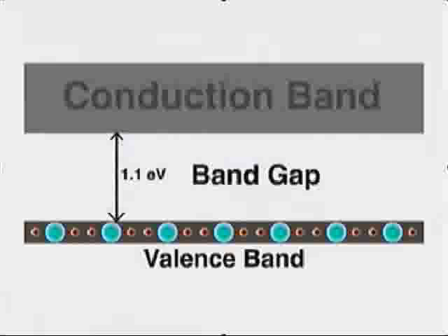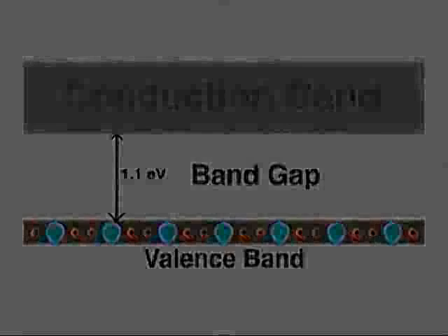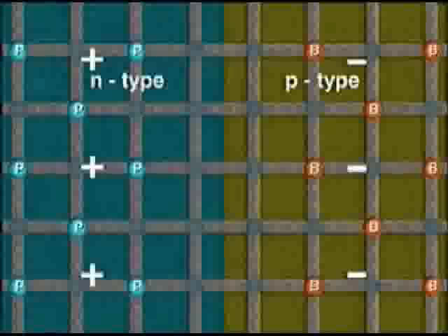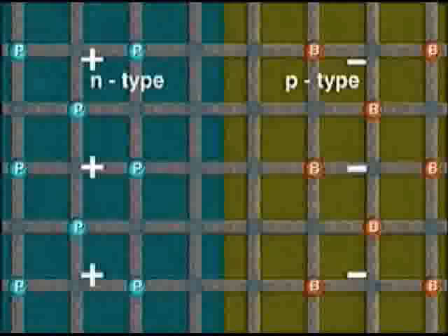However, electrons, once promoted, can spontaneously fall back into the hole in a process called recombination and emit energy in the form of photons. If we are to use the energy of the electrons now promoted to the conduction band to power our electrical devices, we must first separate the electrons from the holes before they can recombine. This can be accomplished with an electrical field. A modern solar cell incorporates an intrinsic electrical field that will separate the charges, giving us the current we need.